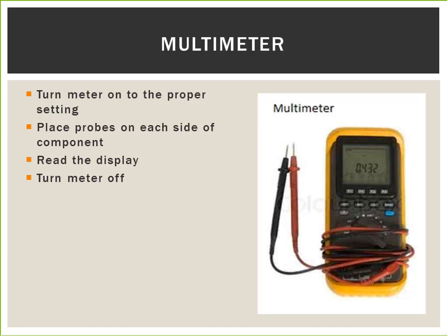Measuring voltage requires the electricity to be on in the device being measured. To measure DC voltage, set the multimeter to VDC. Touch the negative black probe to ground and the positive red probe to the point in the circuit where DC voltage is to be checked. The voltage reading in volts will register on the display with a negative symbol indicating voltage toward ground. A positive symbol may or may not be displayed to indicate voltage moving away from the ground.